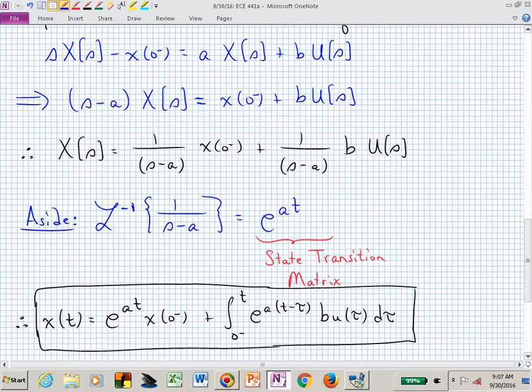And inside that convolution integral is this piece of the state transition matrix. So you're convolving this e to the at, and what does e to the at look like if a is stable? If a is stable, what is little a in terms of its sign? Is it positive or is it negative? Little a. It's negative. It has to be on the real line. It's negative. It's stable. Now we're looking at e to the minus 6t, e to the minus 0.1t. Those are stable, but you can visualize what that looks like.